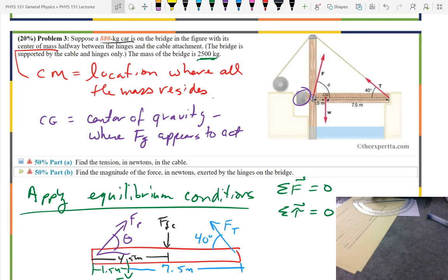And so when you look at a problem, you have 3 unknowns. What's the standard thing that goes through your head? To solve this, I need 3 independent linear equations. But fortunately, statics problems make life a little bit easier because torque is R cross F. If I choose to sum my torques in the right place, I can make R equal 0 for one or more forces. If I make R equal 0 for one or more forces, I eliminate them from my equation. And so there is one location where I have 2 unknowns. What's the one location where I have 2 unknowns?